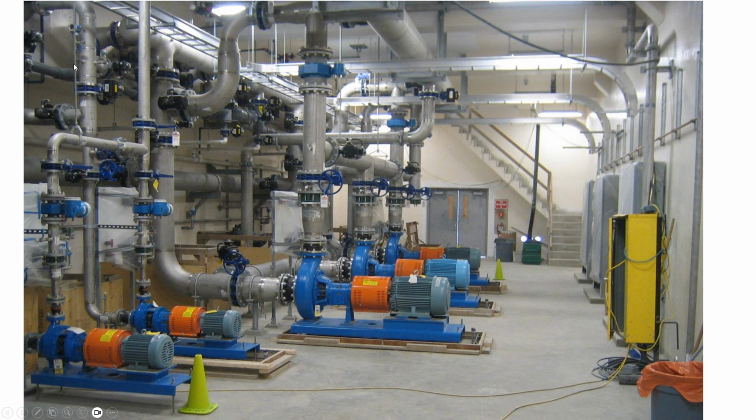This is water that's coming out of sand filters. And if you've taken environmental engineering before, you know that one of the steps in the production of drinking water is that water that's had some coagulant chemicals added to it is filtered through sand in order to get the clay and other colloidal particles removed. But you always have to have redundancy because one of the sand filters may be in a backwash and there may be another one that's getting repaired, and so you have to have many parallel flow trains through drinking water treatment, and that makes the pipe networks very complicated to both design and maintain.